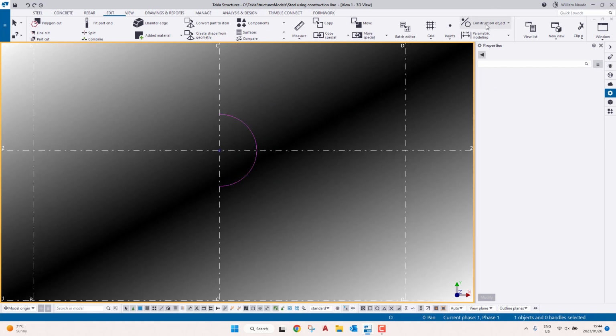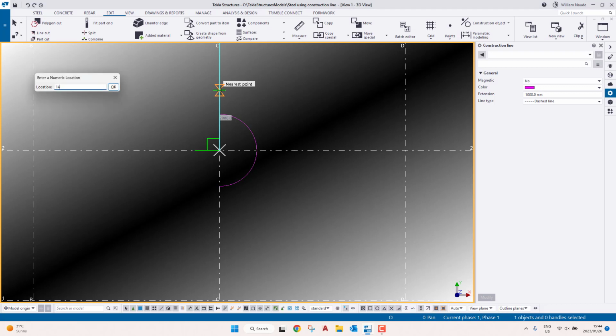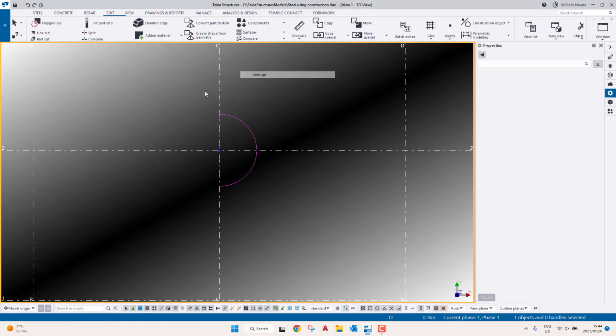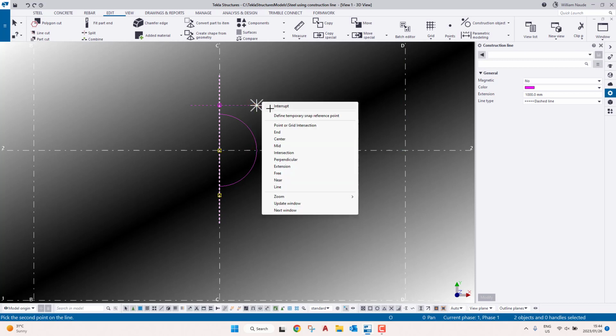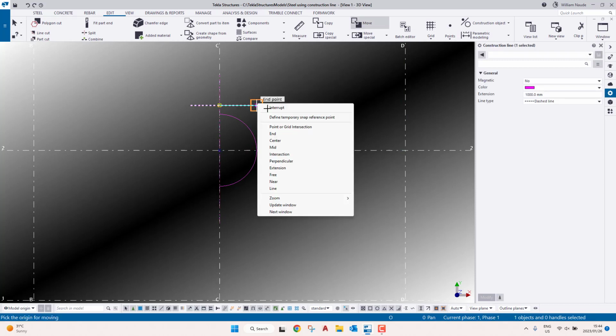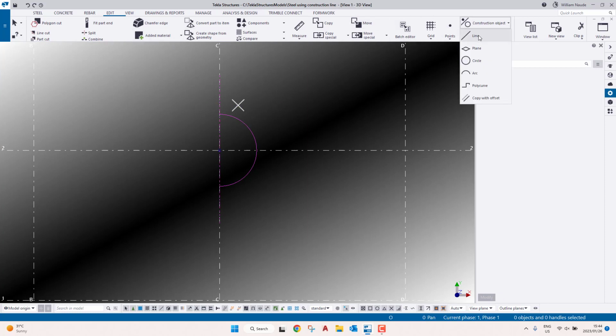So now the next part is we're going to create the construction line with, let's say, 1500, but again 1497 because from center. Copy this, do this, choose these 2, there we go. And now I can draw a construction line that goes again, let's say it is 2000, so it's 1197. That's way too short actually. Let's increase this one. Let's change this one. Let's make it a bit bigger.